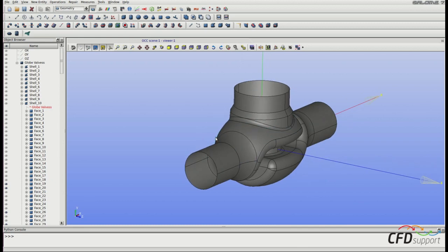The last thing that should be done in this first video is to merge all the necessary faces together to create a shell. At first, deactivate the interaction style switch to be able to select the whole visible geometry by mouse, and select the whole visible geometry.